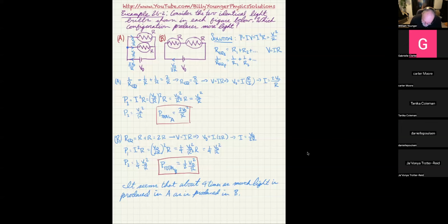All right, so notice in that one I did give you guys your equations for the equivalent resistances in series and parallel. I just want to remind you that they look exactly like the formulas we use for capacitances, but opposite. For capacitance in series, the reciprocal of the equivalent capacitance is equal to the sum of the reciprocals. But when they're in parallel, just their sum gives you the equivalent. Just keep that in mind, and that'll normally keep you straight.